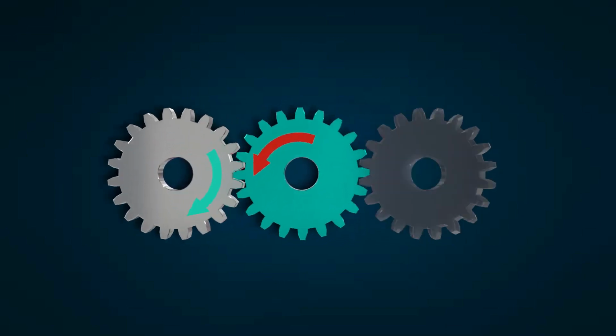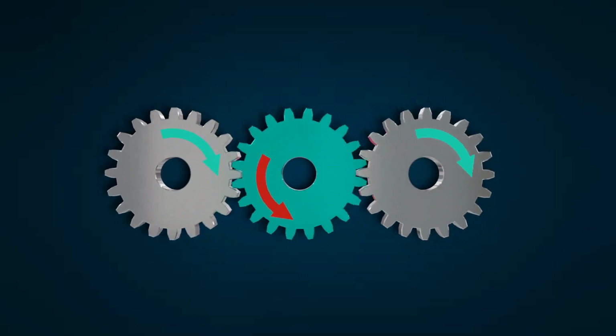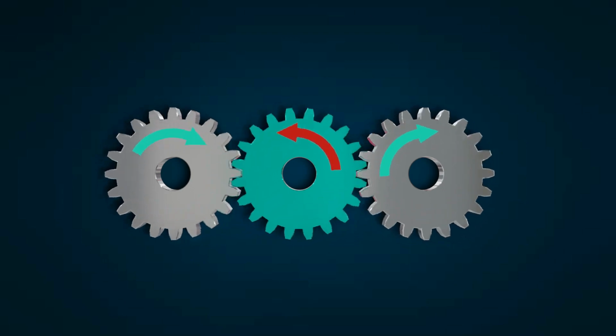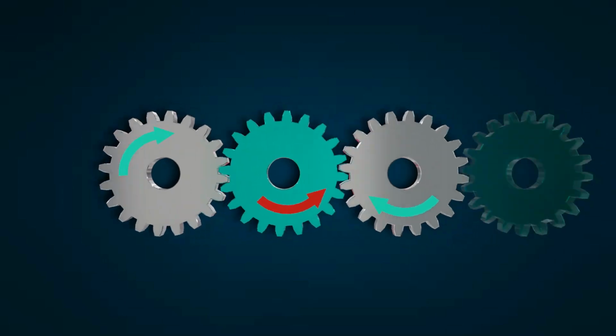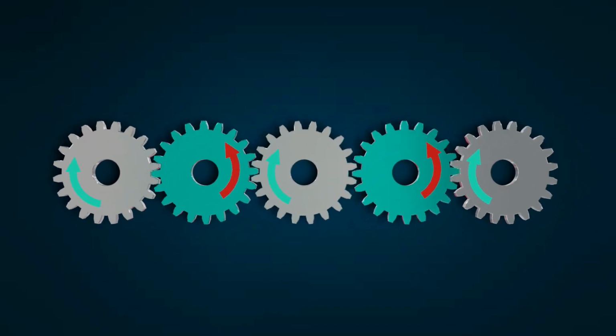This is basically a reverse gear. In order to make the output rotate in the same direction as the input, we need to insert another gear, which creates something known as a gear train. The middle gear is known as an idler gear, which could add many gears side by side to change the speed as well as output direction.